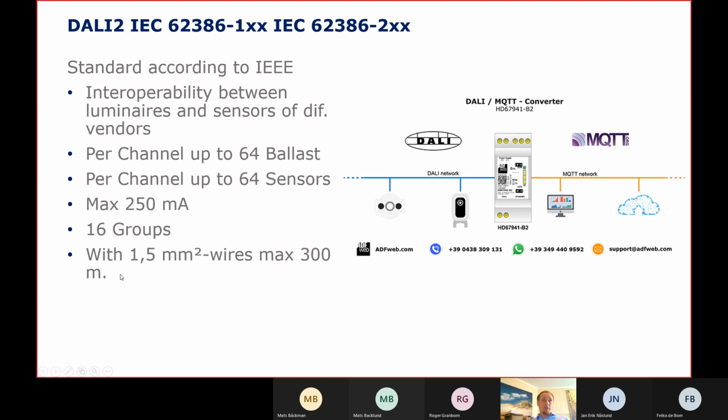So we always need an electrician here. The installation and exchange of a light always has to be done by a certified electrician. And we have the problem that all of these connections are just 7 wires in a daisy chain. So if there's a mismatch or a change and there's a wrong connection, we have to look for where the wrong connection is. It is not failure proof like an RJ45 connection, because you cannot put the plug in the wrong way.